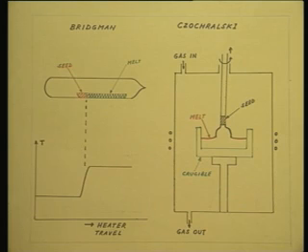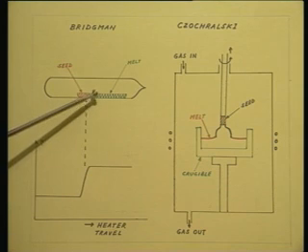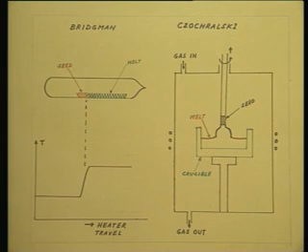When the heater is moving in this direction, that means the end of the melt which is in contact with the seed crystal is now becoming progressively cooler. It is coming in the low temperature zone of the furnace.